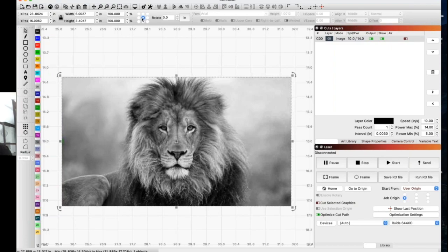Well, don't try that with Jarvis. You're going to be down at 300 to 500 maybe. Pushing the limits, you better be tuned. Your scan offset better be right, your alignment better be perfect, mirrors clean. That's why Lightburn has a built-in warning, because unless you have all that stuff dialed in perfectly, you're not going to achieve those really, really high DPI settings. But we'll stick with Jarvis for right now.